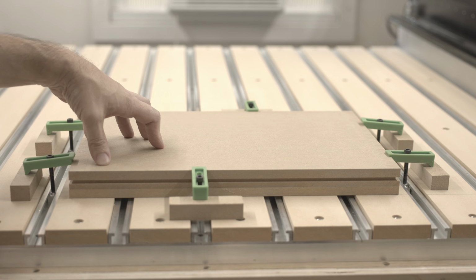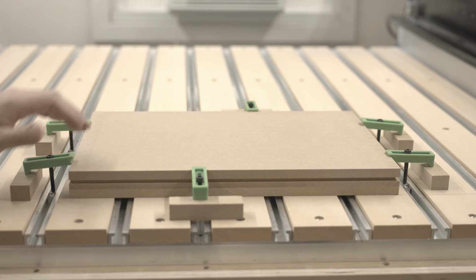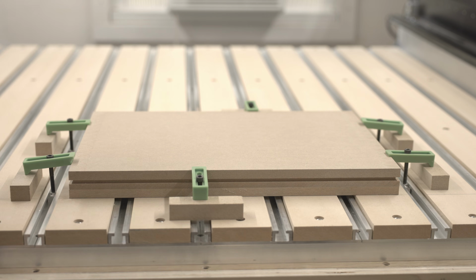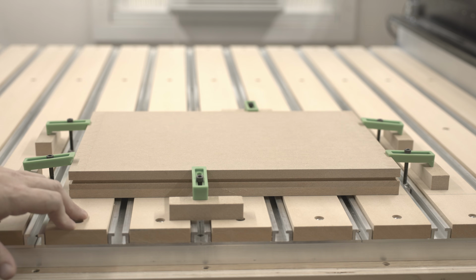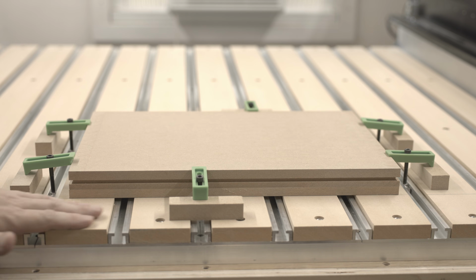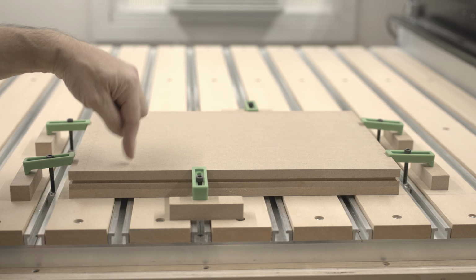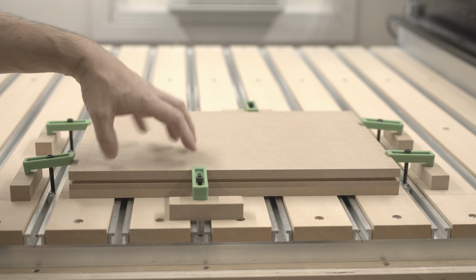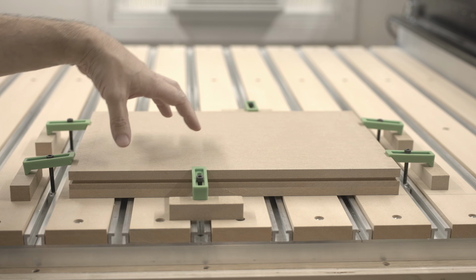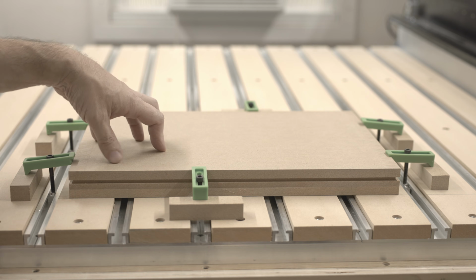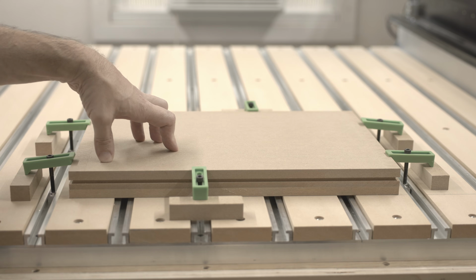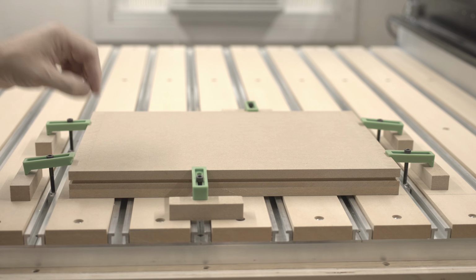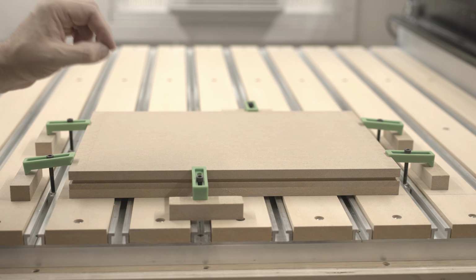And the most important part is to make sure that you've surfaced everything perfectly to your table. You want to make sure the spoil board is surfaced and absolutely flat to your machine, and that whatever you put on it, like these spacers, have also been surfaced so that they match. Everything has to match. Reason being, the photo carving, the little grooves that you cut, the depths of those grooves